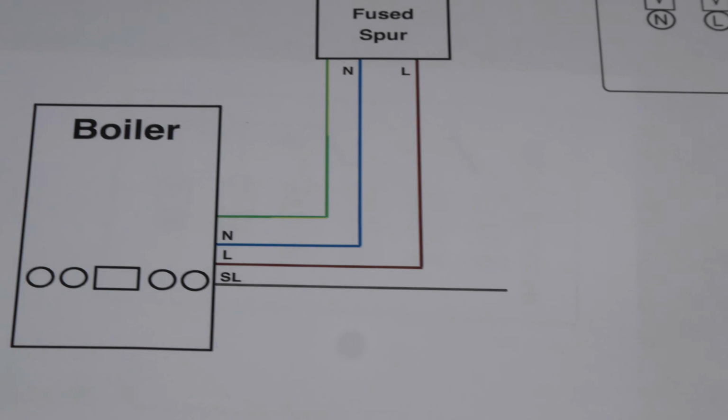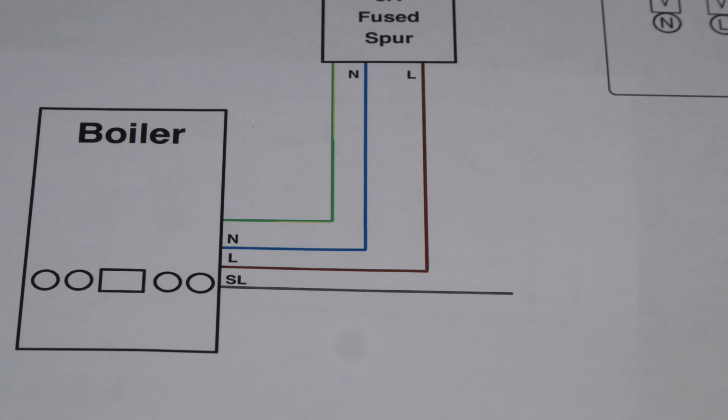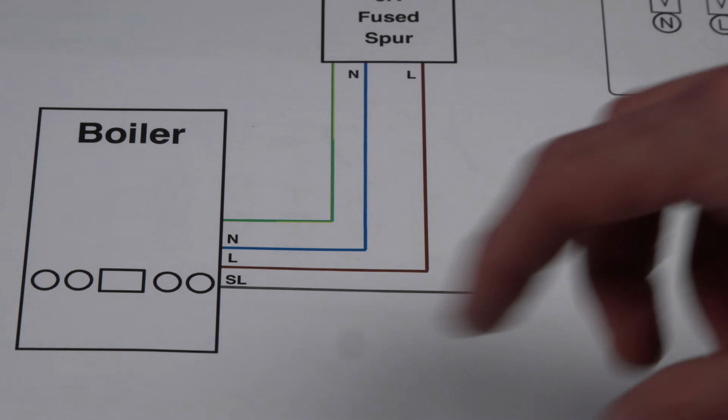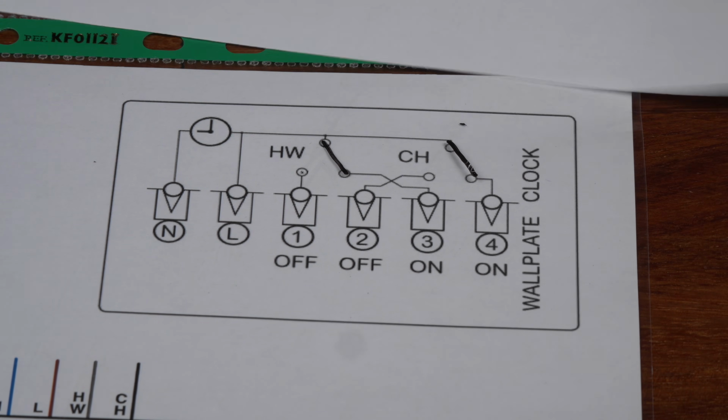Of course, you normally wouldn't buy the multi-channel hub if you've just got a single zone combi boiler, but I suppose there could be a situation where maybe the 2 or 3 channel hub is on a really good price, so you pick it up and just plan to use it with a combi, or maybe you moved house from a place that had a hot water cylinder to a place that doesn't, and you took your Wiser system with you. You can use it with a combi, but just bear that in mind. You don't have dry contacts on the 2 or 3 channel hub.